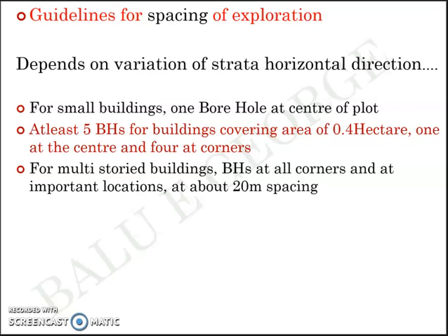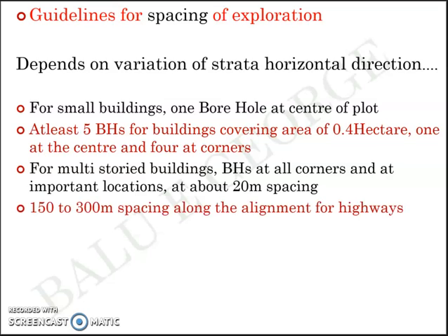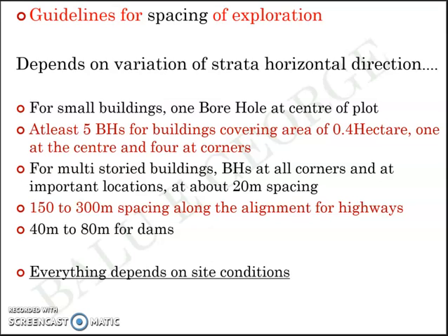For multi-story buildings, boreholes at all corners and at important locations at say 20 meter spacing. And in case of highways, you take the boreholes at 150 to 300 meter spacing along the alignment of the highways. And for dams and other hydraulic structures, you take 40 to 80 meter spacing for boreholes. Again, these are all just guidelines. Everything is under the control and engineering judgment of the design engineer and the site engineer, and everything depends on the site conditions.